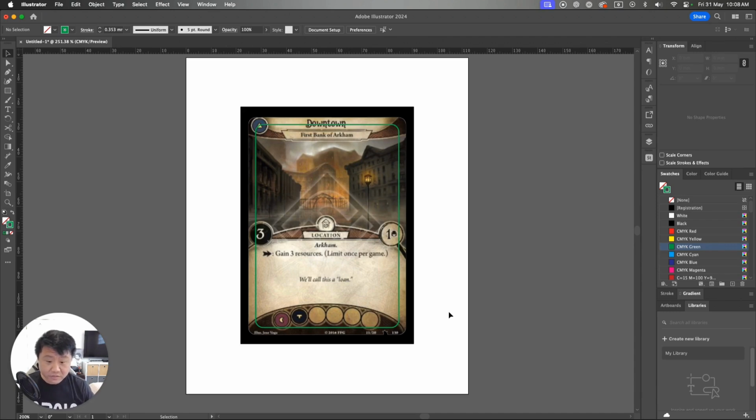Where it does come into effect in manufacturing is that if you keep everything within a certain industry standard good practice, then your design is going to be manufacturer agnostic. Say you're using a local print shop or your own printer, or print-on-demand services that have much higher tolerance error bars; having your text within that 3 mil area is going to be very safe.